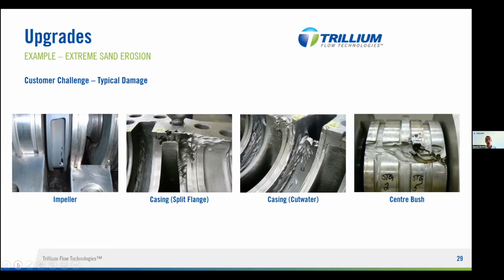And then you've also got the hydraulic issue as well. The actual design includes a cutwater at a certain position, but this is changing the position of that cutwater. So you've got efficiency reduction, and that also leads to vibration and instability. So you've got further problems.